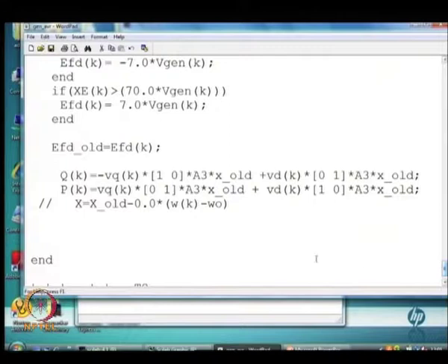What I do here is, I will uncomment this. I will not keep x of the line fixed. I will change x. For example, I change x using this rule. This Kc I give a value of 0.01. So, I am sensing the speed of the machine and modulating x of the transmission line by a controllable device. Of course, the controllable device model I have assumed to be very simple.